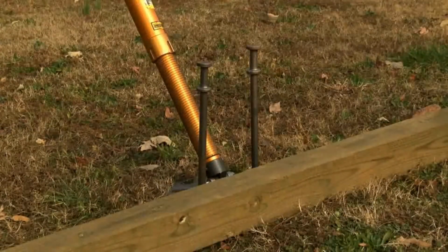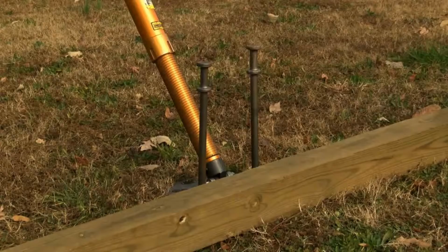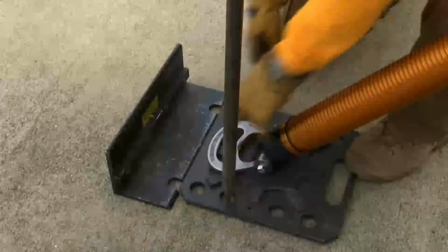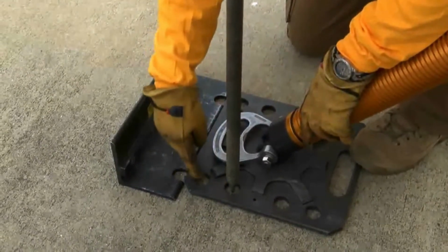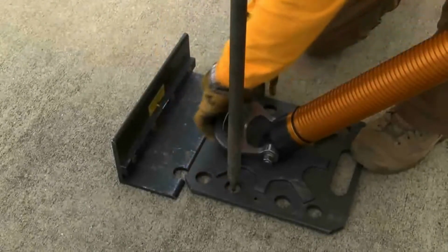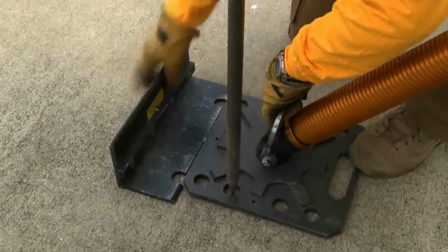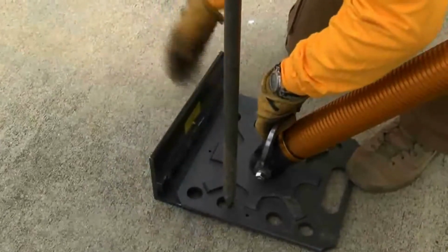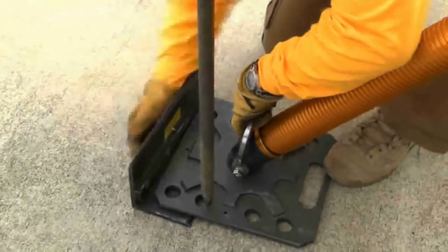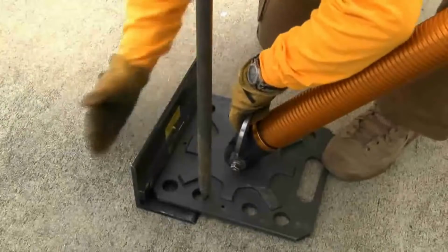If a wooden raker is assembled next to this system, it can be braced to the ground using a whaler. This flexibility is designed in the system. We always place our pickets in the 2nd hole from the back. That way, if a wooden whaler is used afterwards and added a wooden raker, they can slide in the angle brace and fit it right around the picket.